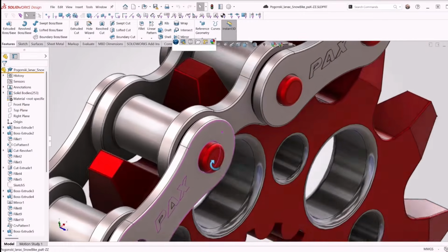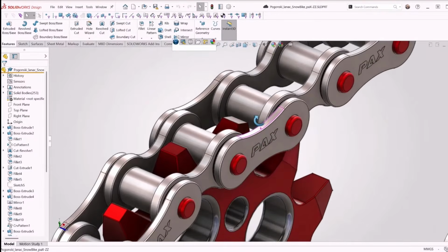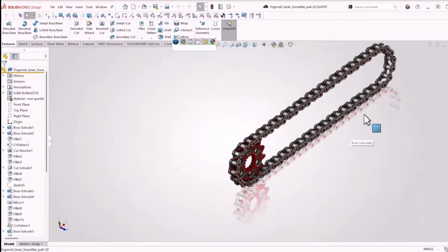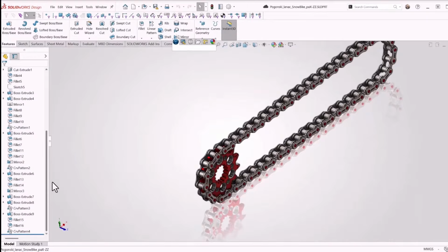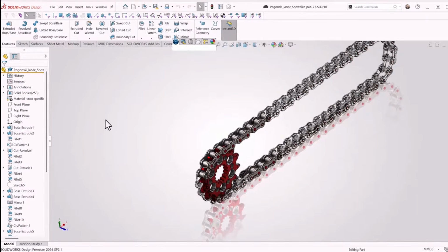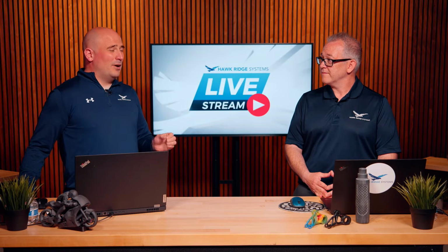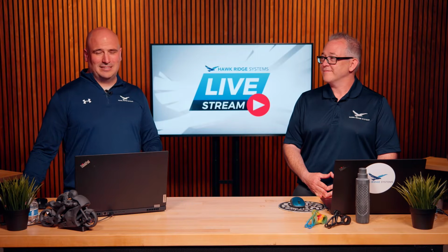Assembly visualization is a little more of a surgical tool. I'm going to open this up and look for three main categories: graphics triangles, opening time, and rebuild time. Opening time is the one you're probably most aware of and worried about. That's the file size, its location, and all the different things it needs to load into memory for the bodies data. Rebuild time shouldn't be too bad as long as you're opening in lightweight mode, but it does play a part when you go fully resolved and have to go into assemblies, components, and all the different levels available.